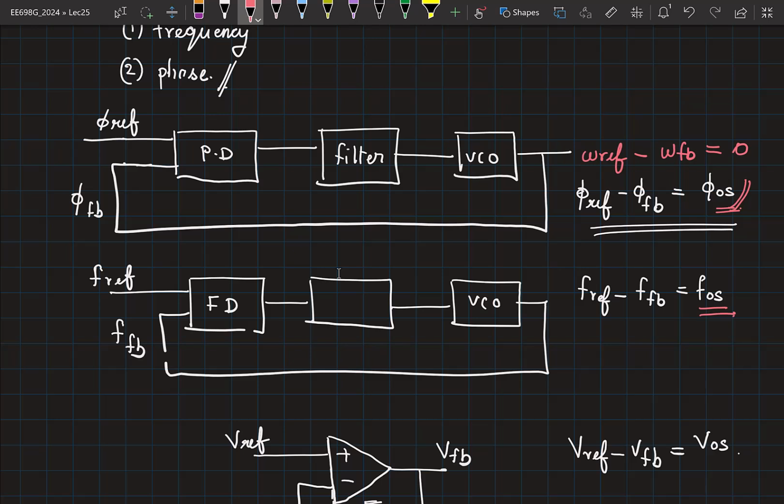On VC, your offset was constant. That is a ripple, the ripple on the capacitor voltage. Now the VCDL delay, you are measuring it at a particular time instant on that ripple waveform. So in every period, you are sampling it at roughly the same position, which is why the offset was remaining constant. Is that clear? You can ask me at the end of this.